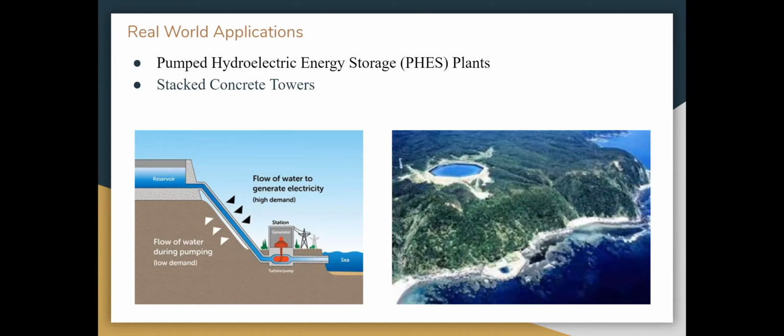The stack towers are a proposed alternative to gravity batteries that have been envisioned to increase efficiency and match that of lithium-ion batteries. Each tower would consist of a 6-armed, 120-meter tall crane that stores energy using concrete or heavy composite blocks. Excess energy would lift the blocks in the air and then be released when the demand exceeds power generated. This will turn gravitational potential energy into electric energy using a generator. Software has been written for the towers to enhance the dropping patterns for optimized power storage. Each tower is capable of storing around 20 megawatt hours.